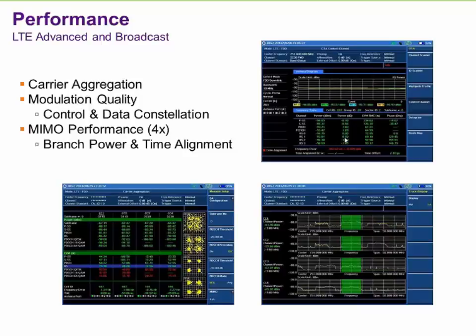I rotated my antenna, and it didn't change. Now I'm really pondering what's going on here, and we came to realize that we were part of a repeater. So the donor antenna that was actually mounted on top of the roof was giving both directional and polarity preference to the first transmit. It was effectively ignoring the second transmit by a factor of 11 dB. So if you basically know signal analysis, you can otherwise determine the various transmit paths. In this case, on a repeater, it was not good at all.